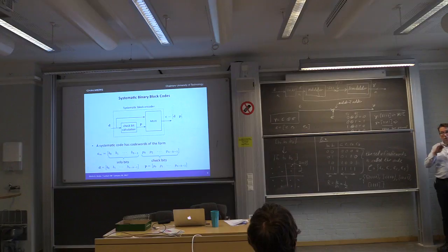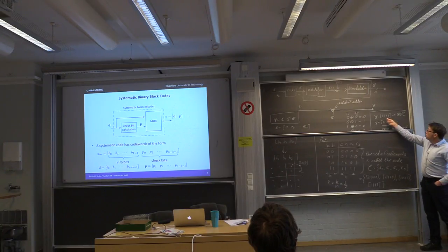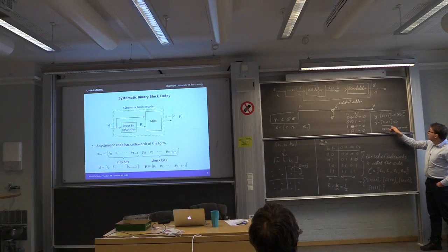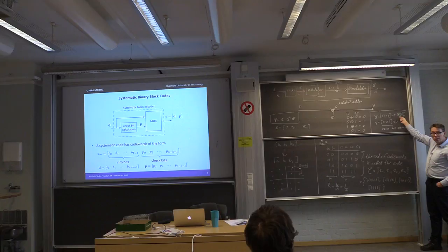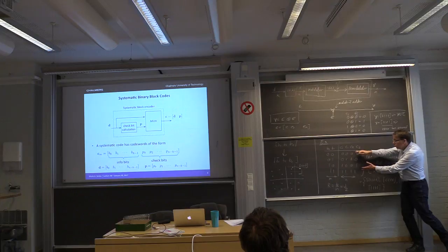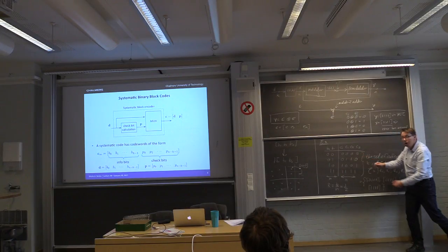This is the basis of error detection: we look at the received pattern, and if it's a code word, then we accept it. This acceptance could be wrong, right? We could accept a code word which is not the transmitted code word, because errors can move from the transmitted code word to another code word.